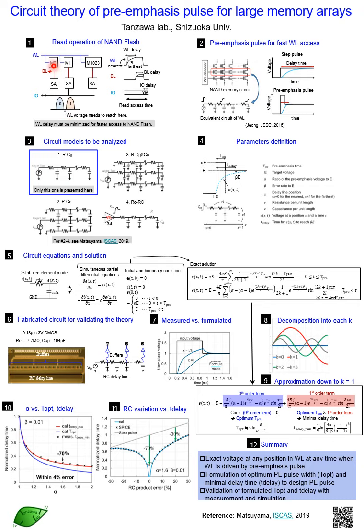Then the bit line should be discharged. On the other hand, the memory cells with data 1 don't turn on with this gate voltage. Bit line voltage should be kept the same as the pre-charge level.